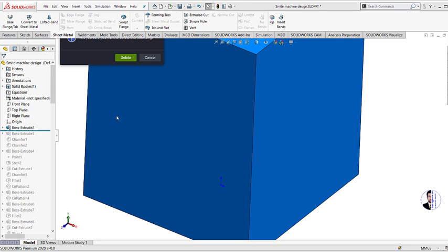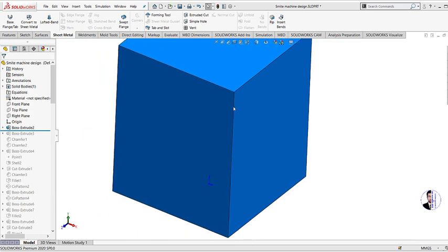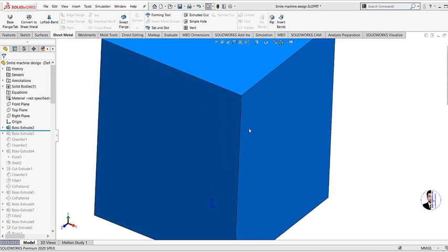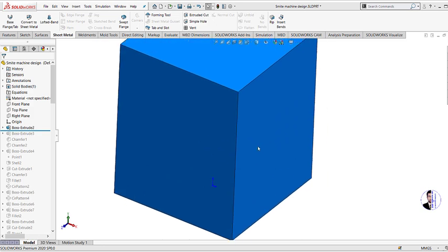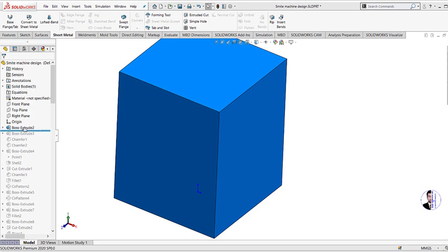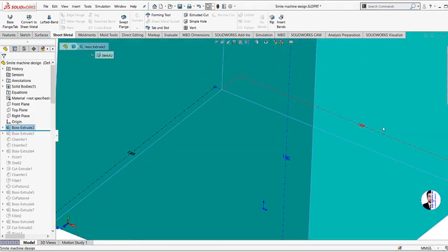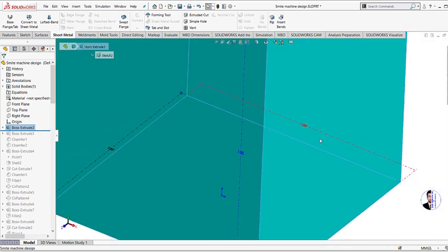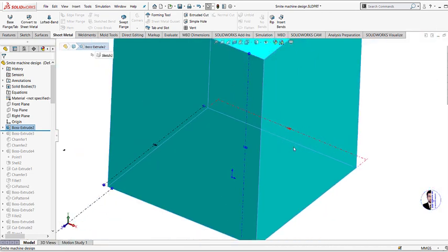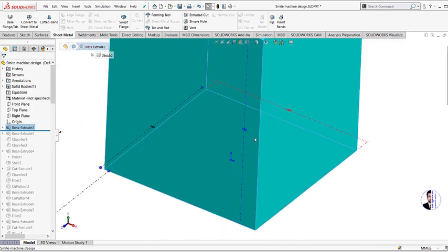Alright guys, so let's introduce the heat transfer press machine. First create the main head box, whose dimension is 125 length and 125 width, and extrude boss 50.